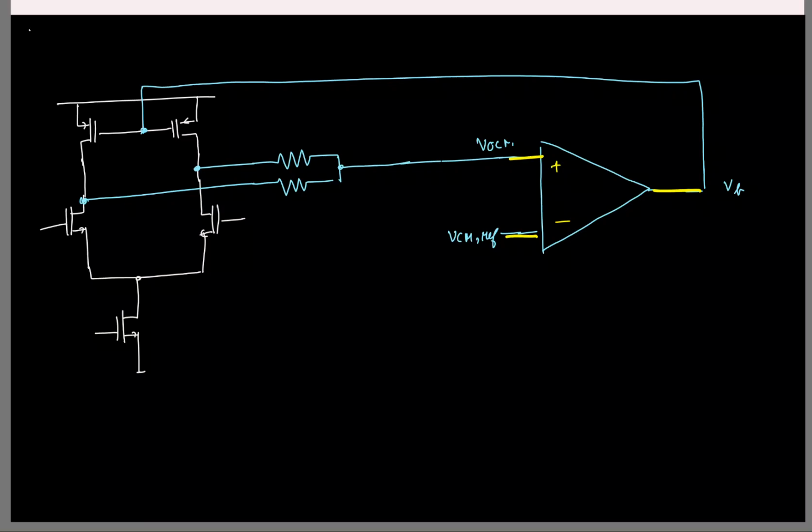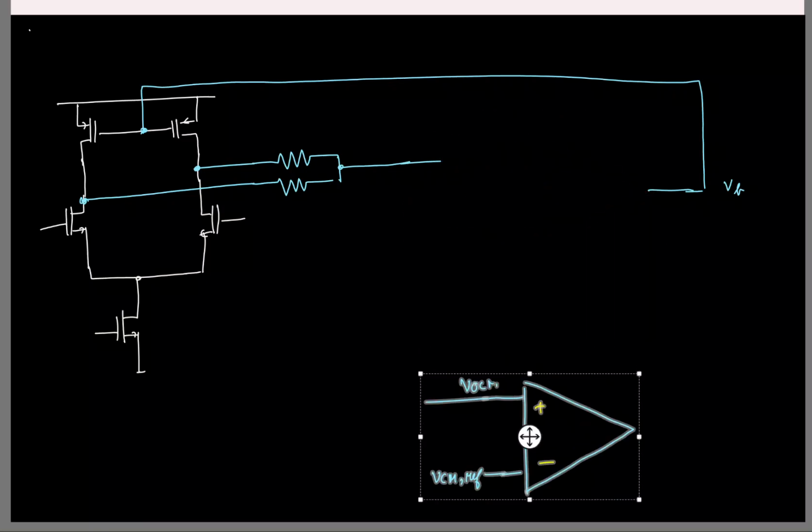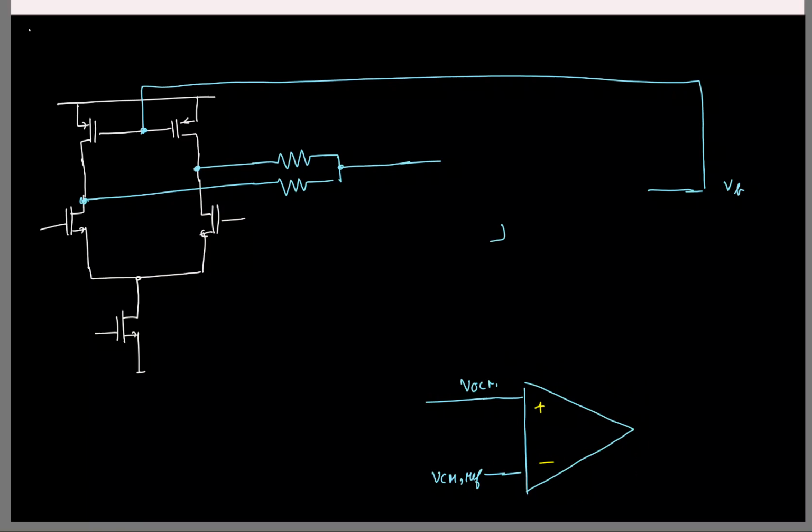What is the simplest circuit you know that can do this? Two inputs and one output, right? OTA. Yeah, it's a 5 transistor OTA. That's the simplest one. So I'll probably first pull this out here. So I'll draw the 5 transistor OTA quickly. So I'm going to have, first, let's draw the output side.